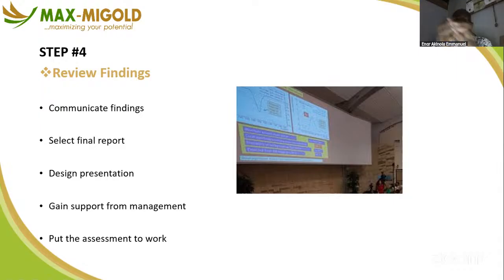And because you have all comprehensive detail about the facility, when you are doing the defense of the cost you want to incur, the management can ask you why you want to spend this money. Then you can easily go to your laptop, bring out the pictorial view. This is the current condition. If you leave this building this way, it's going to crack. That's why we want to make sure we correct the water leakage, and that's why we need to get a structural engineer to do a structural integrity assessment of the entire building. So you have defensible data at your disposal when you are telling them how much you want to spend.